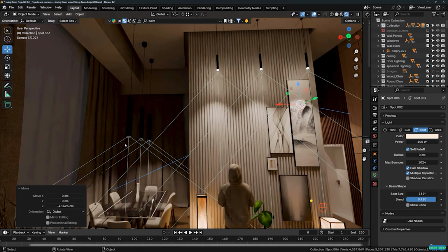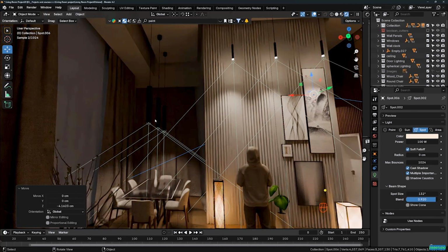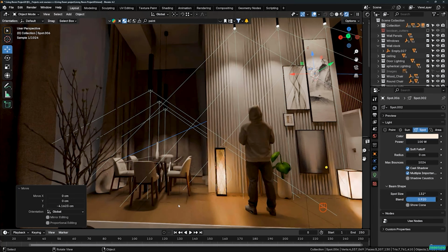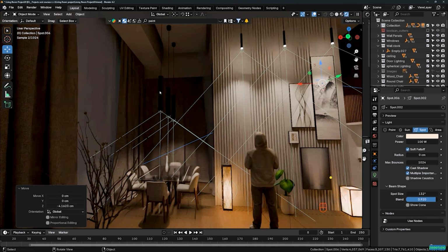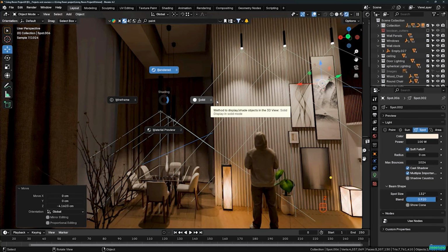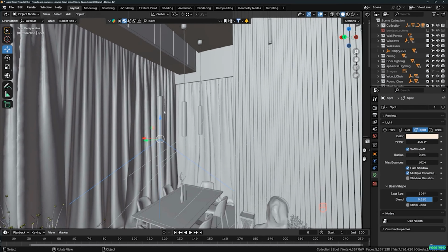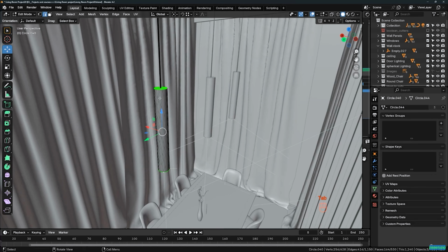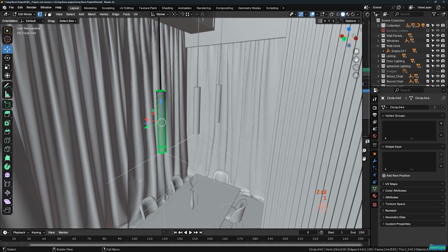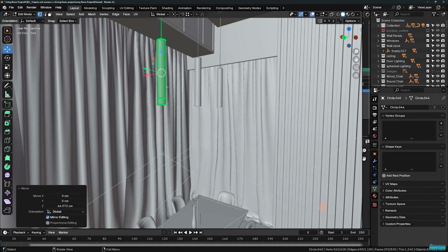One more thing here, I think we should change the height of these three lights. I think we should move them up because the ground level became higher, and leaving these lights at this level does not make sense. So we can go to the solid, and what I can do is grab all of these details and tab to go to the edit mode, and then let's grab all of these vertices and move these up a little bit higher like that.